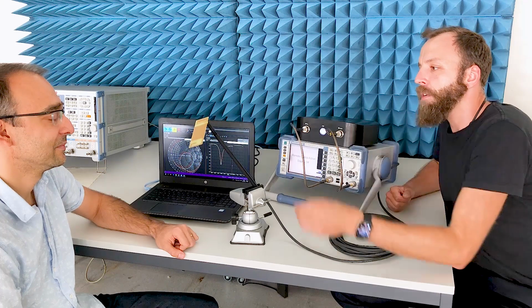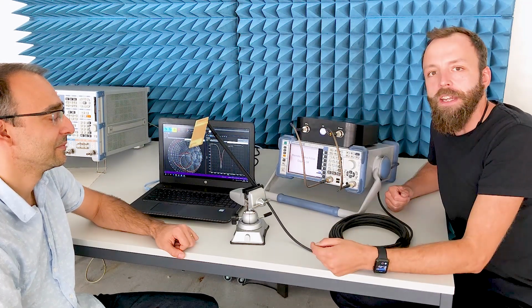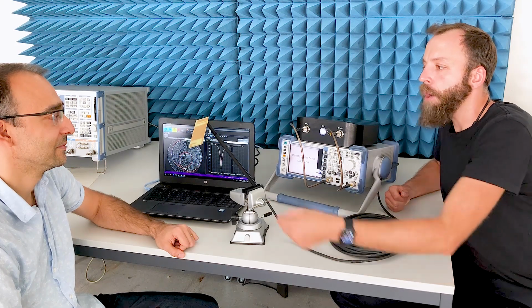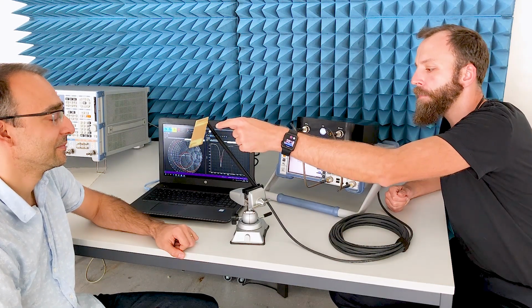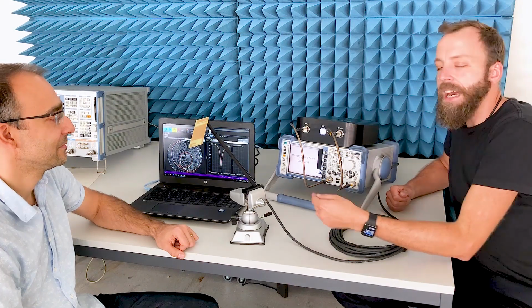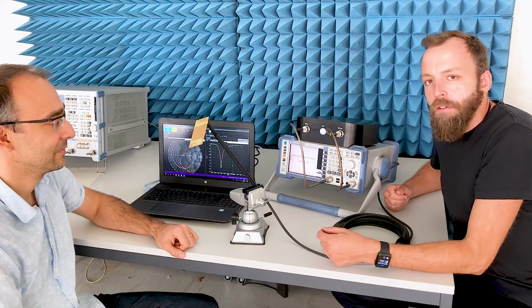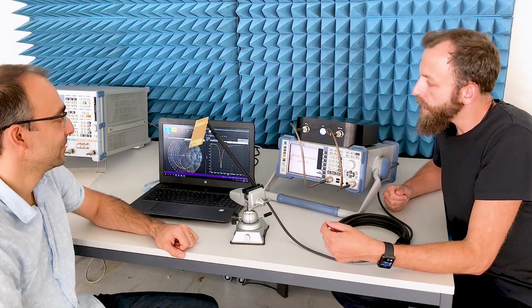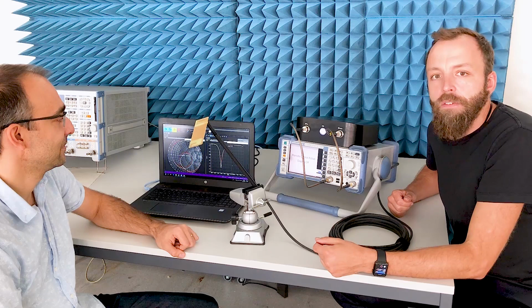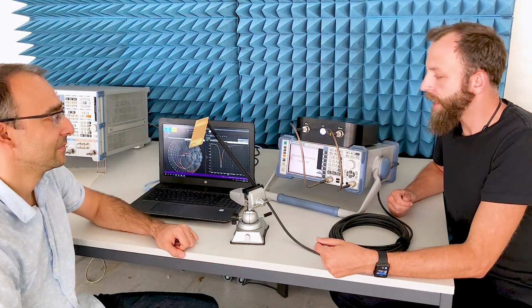Whatever is reflected from that RF signal is sent through a coupler and then again modulated inside the optical head onto an optical carrier and transmitted via fiber optics back to the remote unit, where it gets analyzed on the second port of the vector network analyzer. Together with an open, short and load calibration and the PC-based software, we are then able to compute the S11 parameter of that antenna.